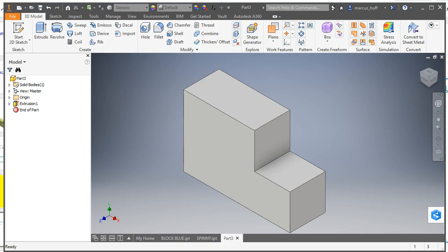So this is one thing I prefer to do, especially making complicated shapes: work in construction lines, then add in the pieces that are needed, and then extrude it as one part all at once. Again, sometimes it's faster just to start over. If you make a lot of mistakes, don't cry over it. Don't get emotionally attached to your parts.